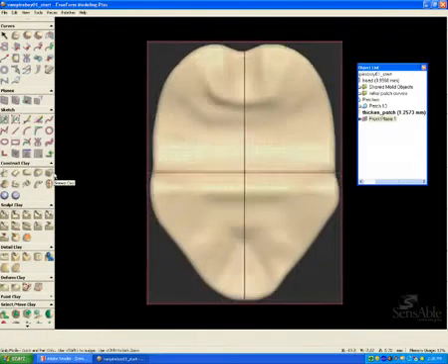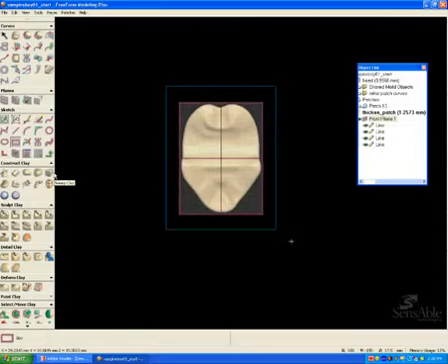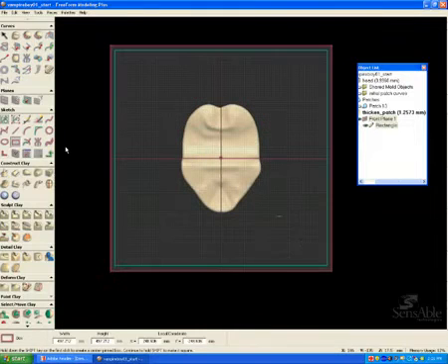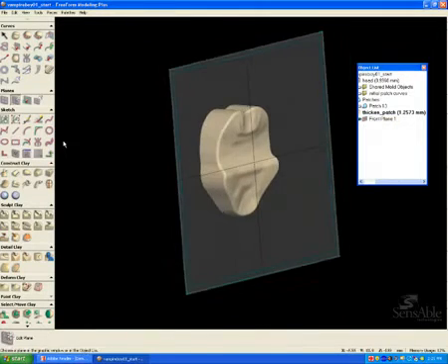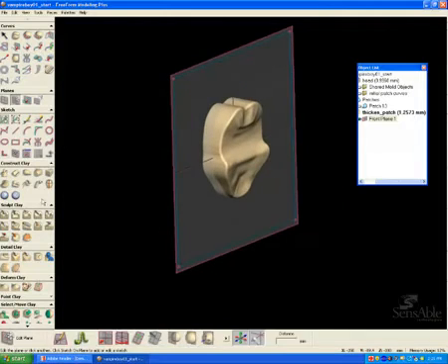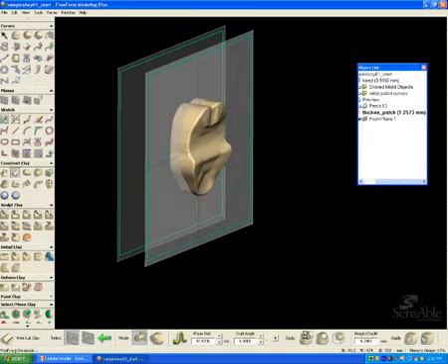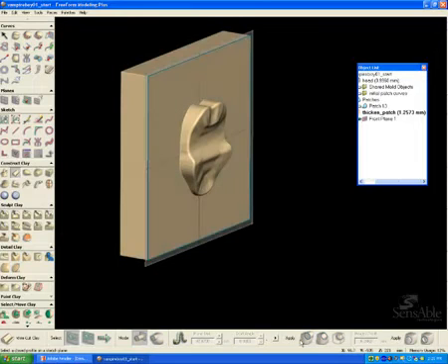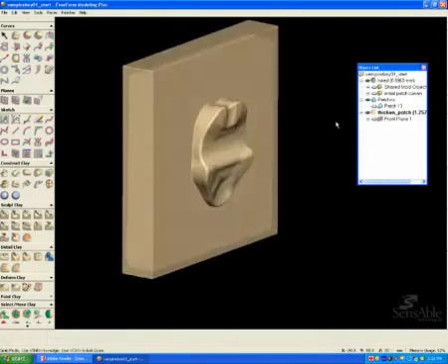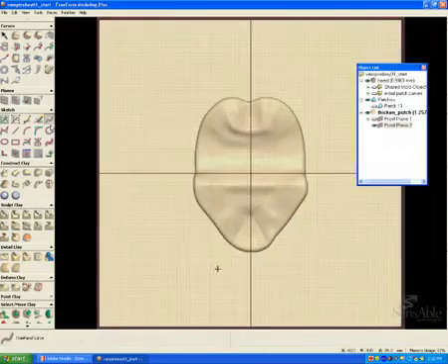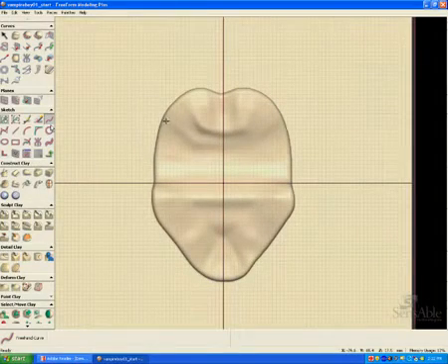So at this point, I'm bringing up a sketch plane, and I want to draw a square in two-dimensional space and then intersect that plane with the complex piece of clay. Essentially what I'm going to do is wire cut a thickness of that box so I can get a basic shape and platform for the insert block that I'll be creating shortly.